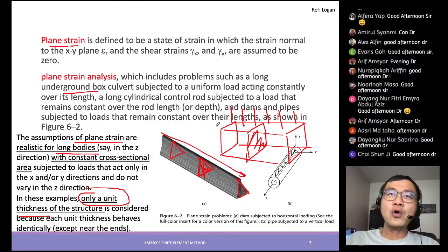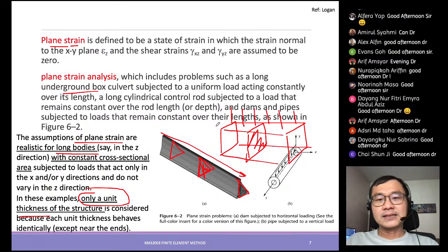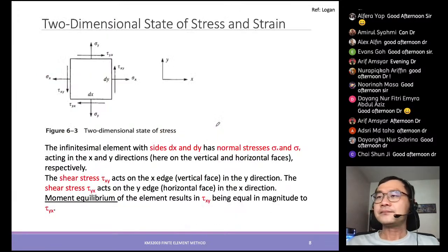If there is a stress concentration, then we may want to move into a two-dimensional problem, okay. When the problem now becomes more complicated with changing shapes throughout the three-dimensional or xy directions, then in that case, we may want to further increase the degree to a three-dimensional problem, right.